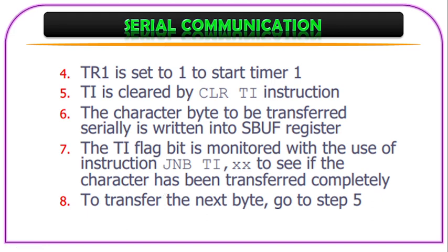And then you start your timer. For starting the timer, TR1 should be made 1. Set this timer run bit to 1 to start the timer, and then clear your transmit interrupt flag of the serial control register. And then the byte which has to be transmitted should be put into the SBUF register.